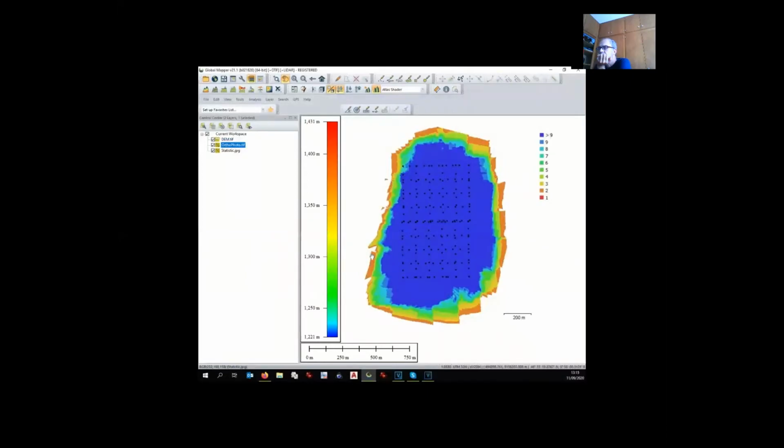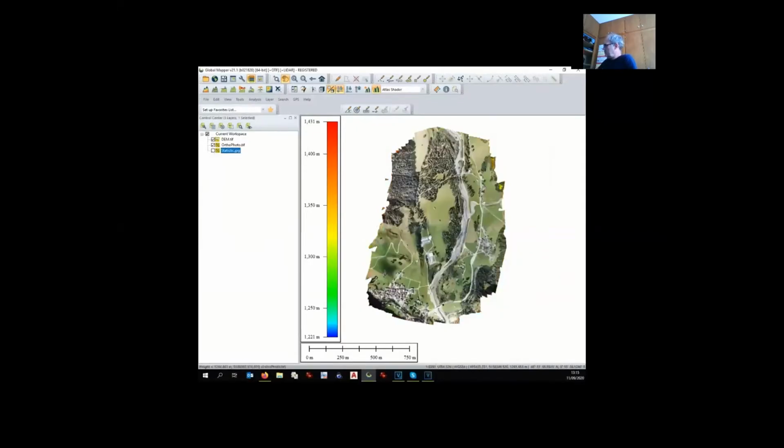Yes, it is precisely georeferenced. As we know, the blue area has the highest overlapping. It means it has the better quality. And for our purpose, we consider only the blue area. You can cross-check this information looking at the orthophoto.